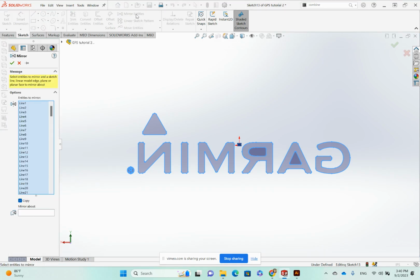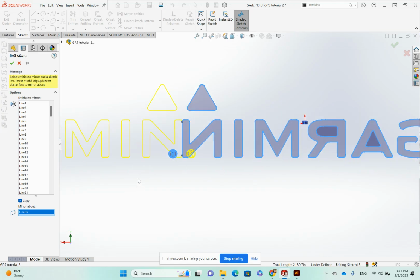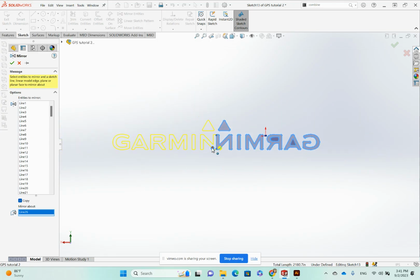So I'm going to click Mirror Entities. It's asking what I want to mirror around. It has them all highlighted. These are the entities that it's going to mirror. Basically, these are the chunks of the sketch that are going to get mirrored, which is everything. It wants to know what I want to mirror it about. I'm just going to pick any vertical piece. I think that'll work. Okay, I click this vertical far left side of the N. Now the yellow is the preview of what's going to happen. That looks great. So I'm going to click check.